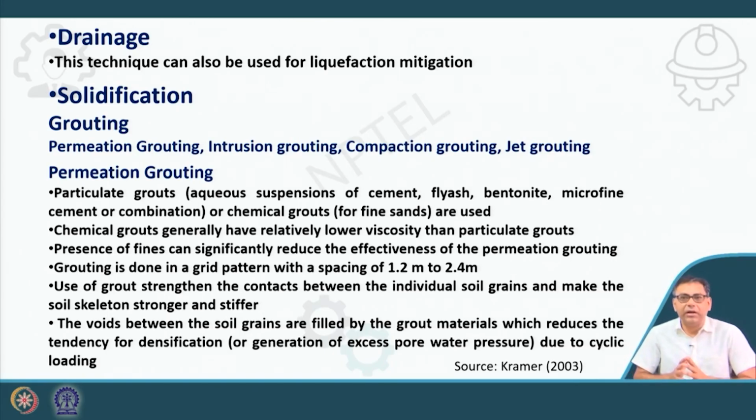Now, if the soil is loose and there are voids, and it is a saturated soil, then during cyclic loading, because of the presence of water pressure within the voids, there is a possibility of generation of excess positive water pressure. Now, if these voids are filled with grout material, that means the generation of excess water pressure is reduced,